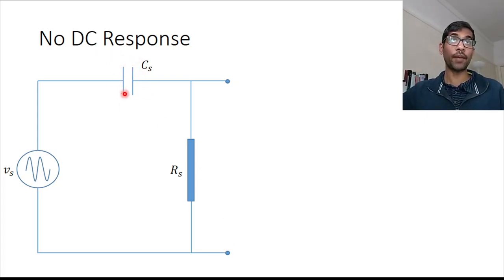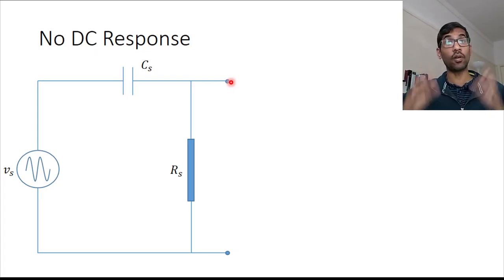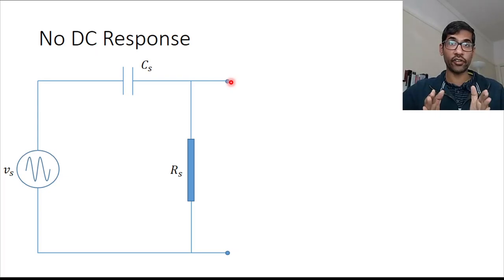Because this capacitor is here, it is going to block any DC voltage at the output. So if you have a constant charge across the plates of a capacitor or across the plates of a piezoelectric crystal, that's going to disappear. Okay, and that kind of results in the first property of piezoelectric sensors. Piezoelectric sensors can only detect changes, they cannot detect constant forces or constant strains.